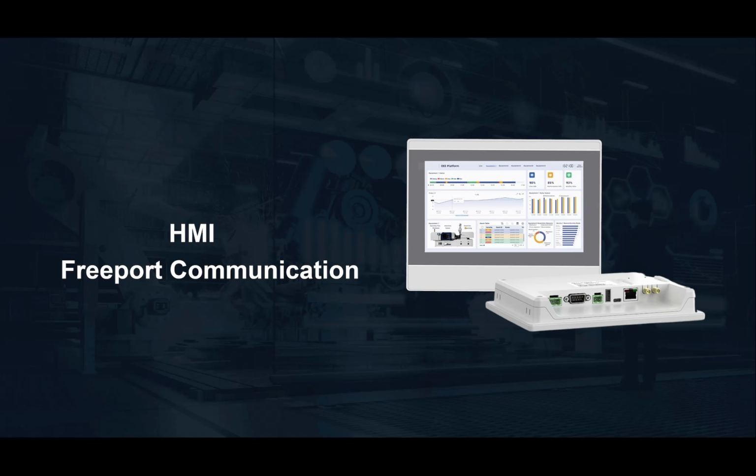Today we will go over Freeport. Freeport Protocol is a flexible serial communication feature available on human-machine interfaces, HMIs, that allows users to define custom data exchanges between the HMI and external devices, e.g., PLCs, sensors, or proprietary hardware.